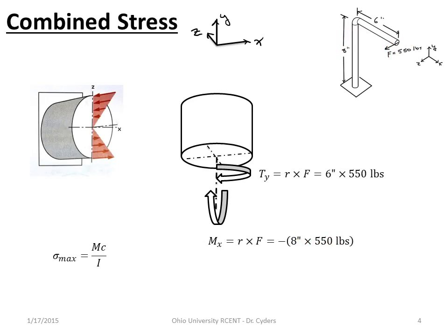To remind ourselves what the stress distribution looks like due to a bending moment, we have compressive stresses here on the side with the z-axis. So we have compression over here, and we have tension on this other side. That'll matter because we have positive and negative, and if we want to combine stresses, those things are important. If we were to orient it to the original diagram, we have compression here, and that makes sense because if I were to grab this thing and pull it this way, then I'm going to compress this side of the beam, and the far side of the beam I'm going to be stretching. So I've got a maximum stress, MC over I.